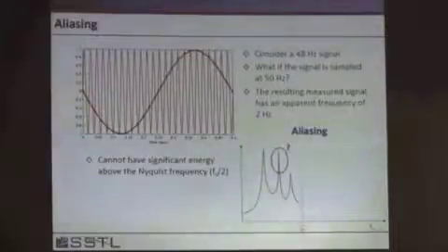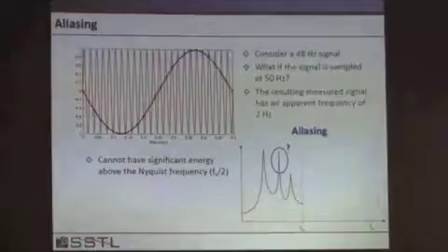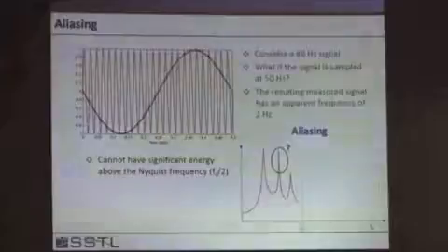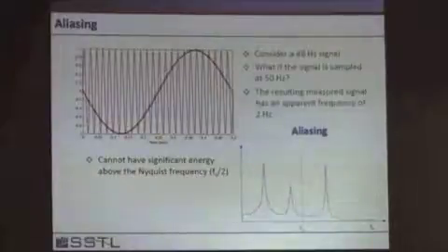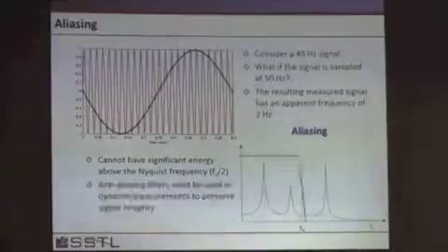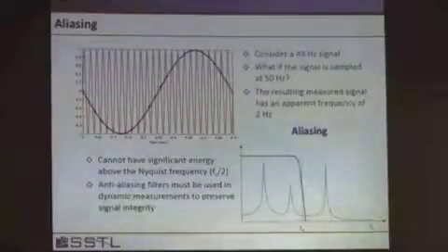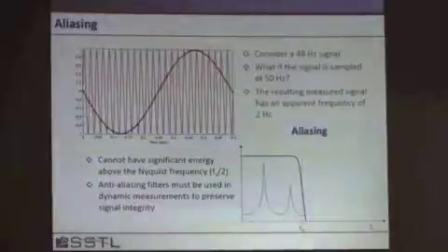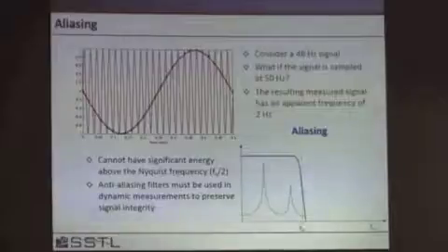This would be the measured response if you didn't have anti-aliasing filters. So it would look like you had 3 modes in your baseband frequency, but one of them was due strictly to the digital signal processing, bad digital signal processing. Once you've sampled your data, you can't get rid of aliasing. Before you sample the data, you have to apply an analog filter which wipes out the higher frequency response. Now when you sample the data, you can get clean signals that can be used for your analyses.